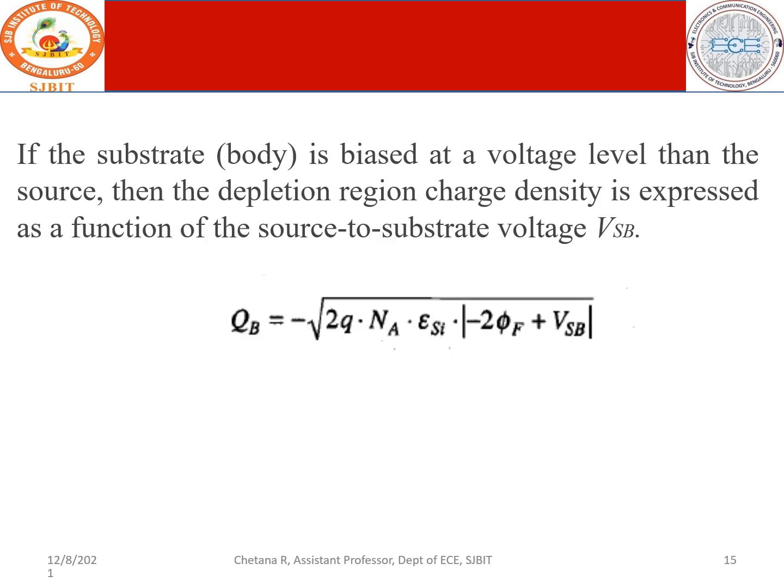So sometimes we have seen that the substrate is always connected to ground. This is done in order to eliminate the effect of body, or in other words to overcome the body effect, or whatever junctions are being formed in the substrate that are responsible for the leakage current. So to overcome that, the body is always grounded. Therefore, it is neutralized, and as a result the junctions are not created.